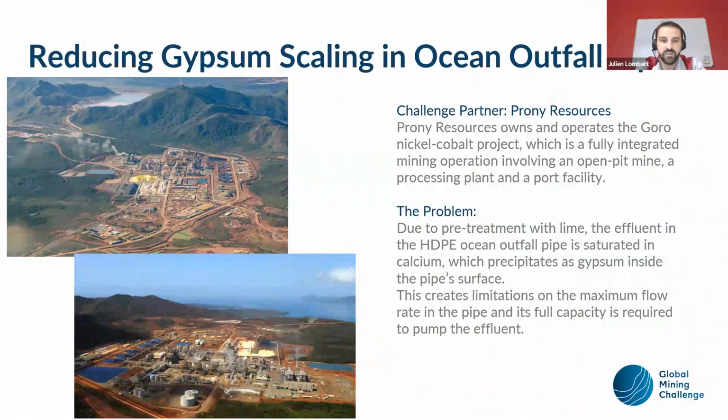And then we feed the liquid solution, the PLS, the pregnant solution, to a step of neutralization. We neutralize with limestone in the first step and then with lime. After that, we arrive at the last part of the process where we will precipitate our final product as MHP using magnesia in the process.